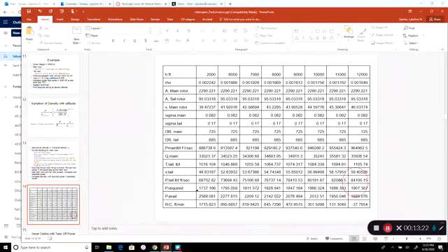Compare with available power. Note that the available power is decreasing because the density is decreasing. Then whenever these two things are roughly equal, in this case within 18, you have reached the absolute ceiling. To do the service ceiling, you'll take power available minus power required by weight.